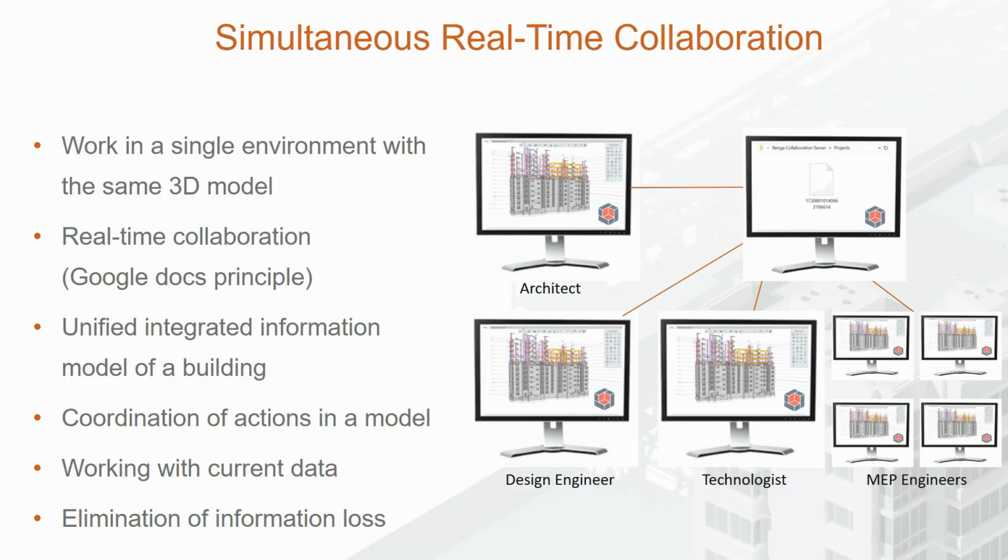One of Renga's main advantages is its unique real-time collaboration functionality. It works in a similar way to Google Docs. If your colleague adds an object to the model, you will see this object immediately. In Renga, all project members work in a single environment with the same 3D model. Each project team member can track the changes that their colleagues make. This reduces the chance of collisions between architectural, structural, and MEP solutions and reduces the time taken for model coordination.